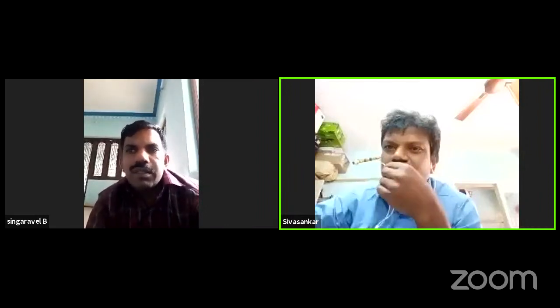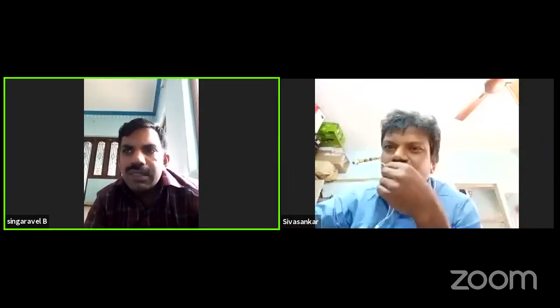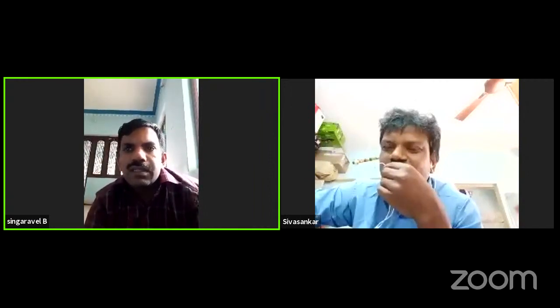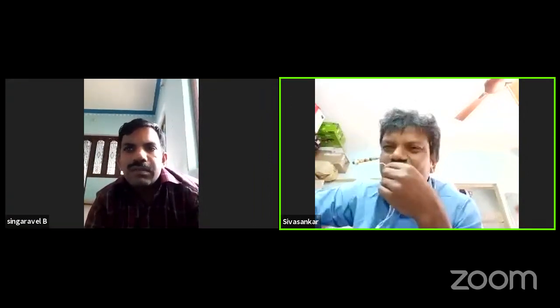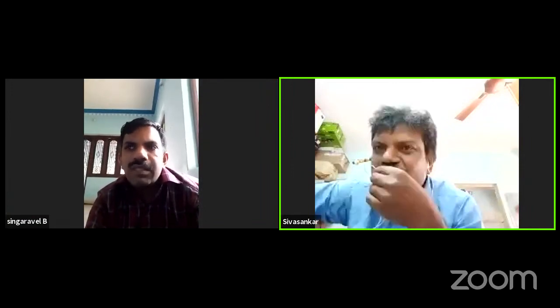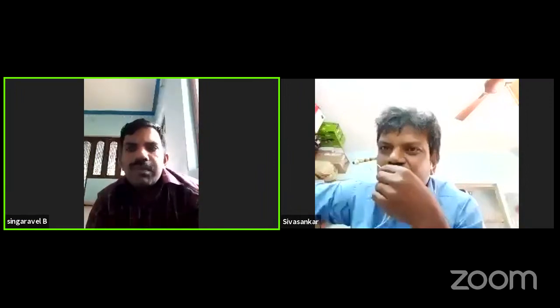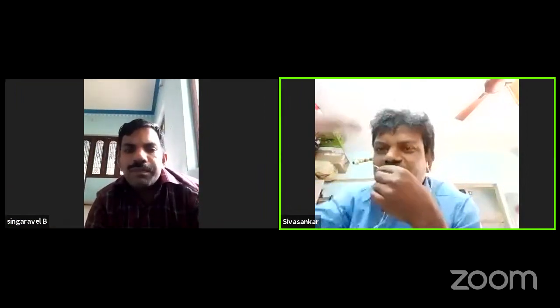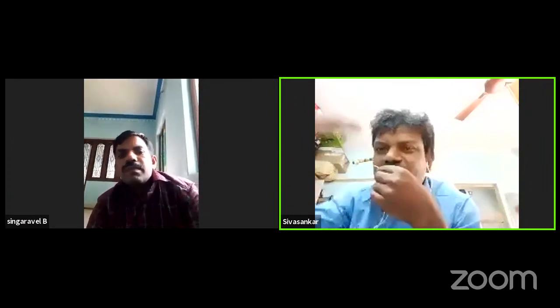What is the difference between normal gray relational analysis and entropy based gray relational analysis? In normal gray relational analysis, we are giving equal weight. Here, for example, if there are 6 outputs, you need not assign the weight.